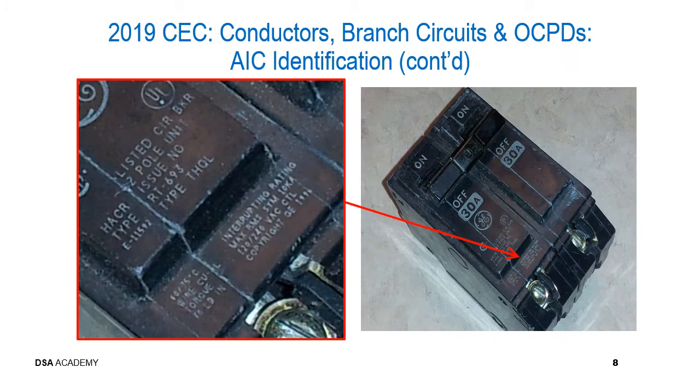These two photographs show an image on the right of a typical two-pole breaker, and as you can see, if you look at the handle, you can see that there's definitely a tie bar attached. And the tie bar itself makes sure that when these breakers are shut off, they're shut off simultaneously, and when they're turned back on simultaneously, because that's a critical function of the equipment or the components that are energized upstream